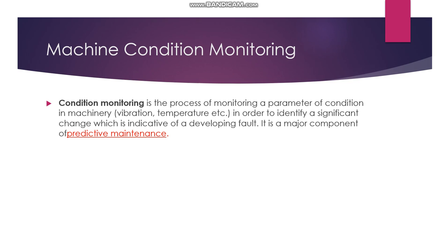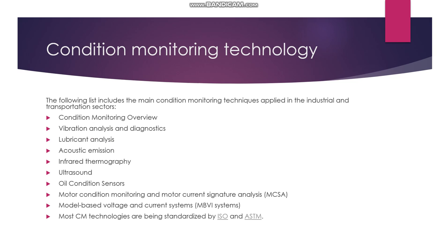Condition monitoring techniques are normally used on rotating equipment, auxiliary systems, and other machinery such as compressors, pumps, electric motors, internal combustion engines, and many others, while periodic inspection using NDT (non-destructive testing) techniques and fitness for service (FFS) evaluation are used for static plant equipment such as steam boilers, piping, and heat exchangers.